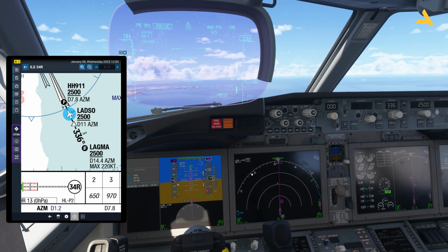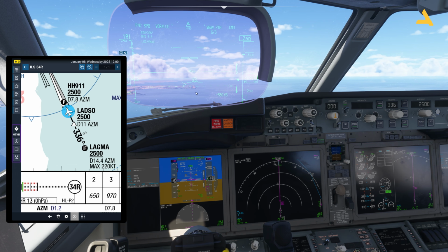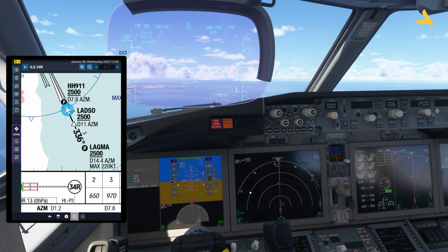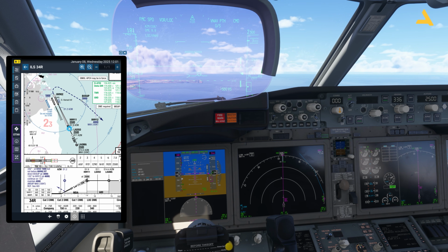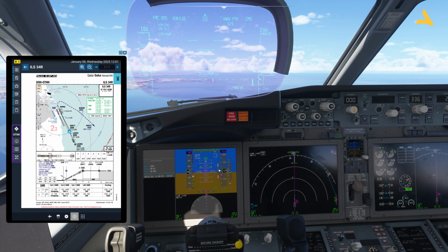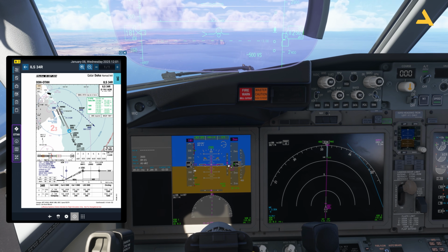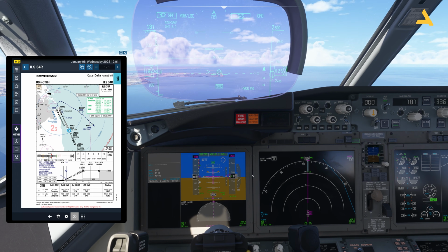Now in this mode, the autopilot will not only fly this straight flight path, it will follow this lateral flight navigation, but also follow the glide slope, which is this one, 3-degree descent towards the runway, as soon as this diamond is in the middle. So this is for the lateral navigation, and this is for the vertical path. And now you can see the plane has started to descend towards the runway.